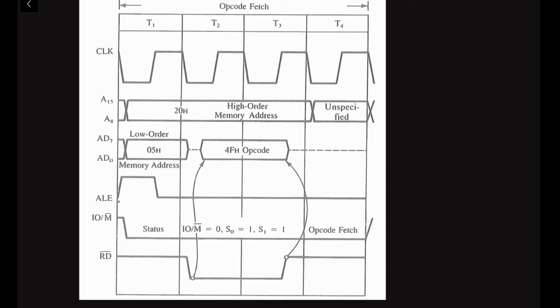So this is for the 8085 microprocessor fetch operation. This is the opcode fetch operation. Opcode fetch means the operation code is read from the memory. Basically it is a read operation, but during this read operation we have an extra clock cycle, the T4 clock cycle, which we have to understand. After getting the opcode, it is decoded in the T4 cycle. Why do we require this extra cycle? Because the microprocessor has to decode the opcode,